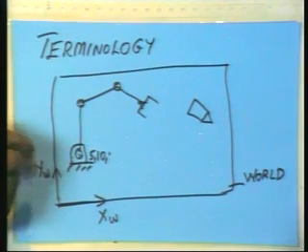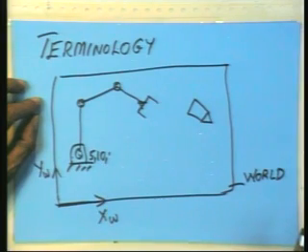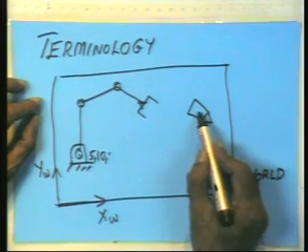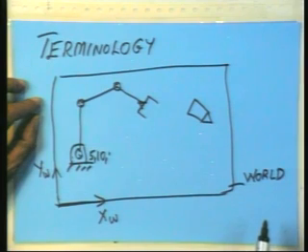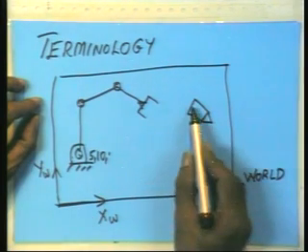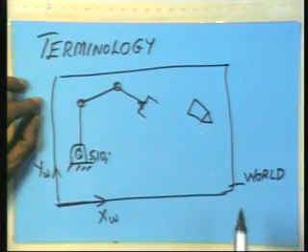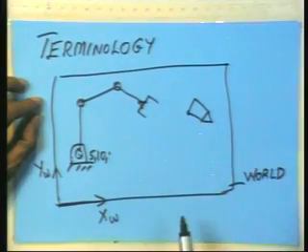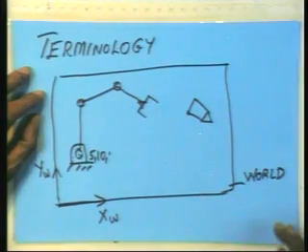This is where the robot is. Then he asks me, where is this object the robot has to pick? With a scale I can measure where the object is, and give him that. Of course, I have to specify a point on the object. Then I tell him, go and bring a measuring tape and measure all these things, and the robot base of course. So it makes sense to find out where the robot base is by using a measuring tape or looking at the drawing based on which the robot has been fixed to the table.